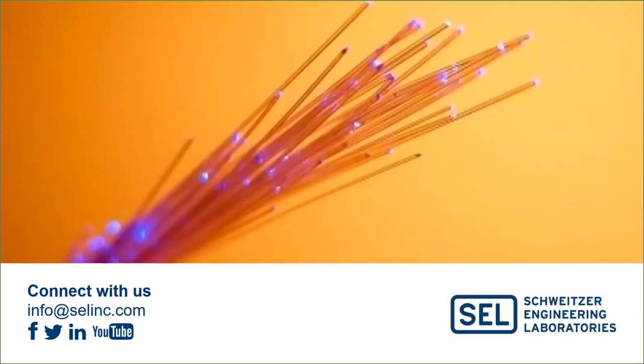Do we require a transceiver to pass Ethernet data over fiber? The answer is it depends on what the native port is. If we have a native fiber optic Ethernet port, then you just hook right into it, usually with your LC connectors. If you have a copper Ethernet port and fiber optic Ethernet coming in, then you'll need a separate device.